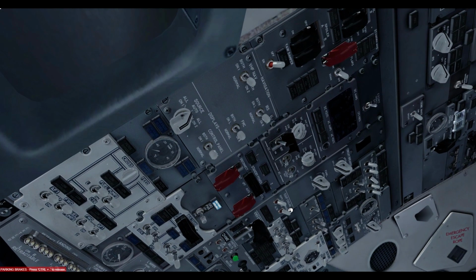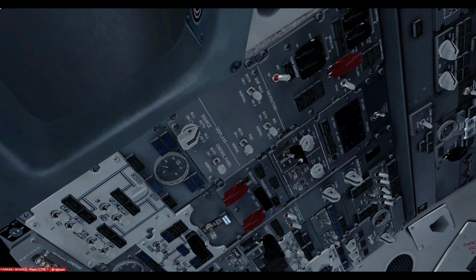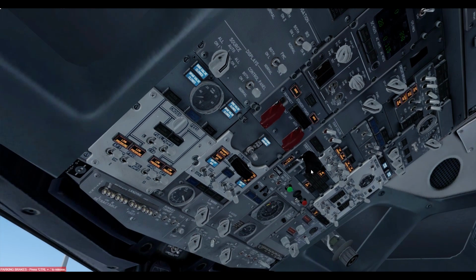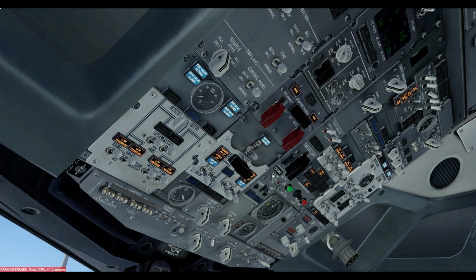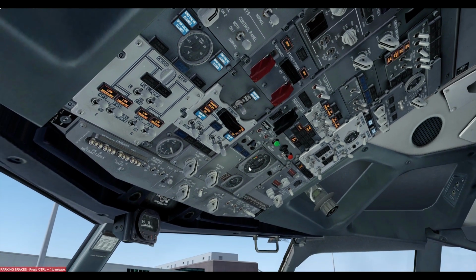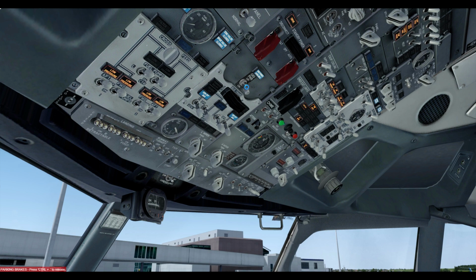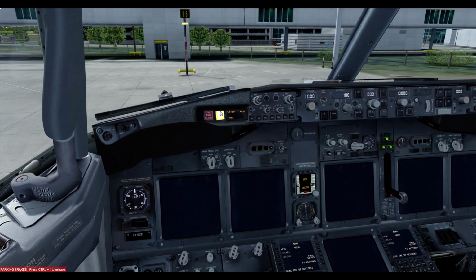So what you want to do is go to the overhead panel and find the battery, which is here. You set the electricity switch, which basically just displays what power source the airplane is using. Set it to ground power. You close the emergency exit lights. Chime can come on if you want to. You can just play with that if you want to. Logo lights. Also, I tend to turn off the recirculation fans, which are over here, because they are very loud and can be a bit annoying. So once you've done all that, you just click this here, ground power on, and the plane is online.